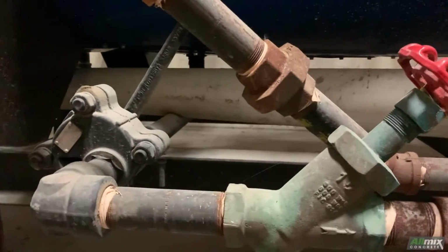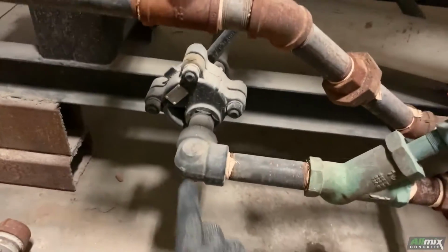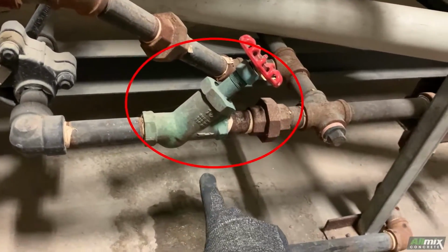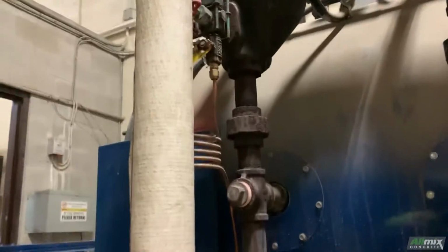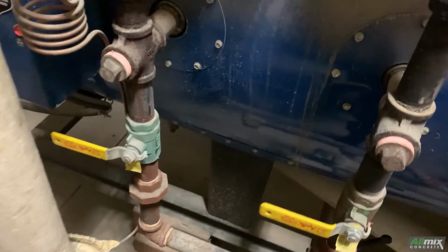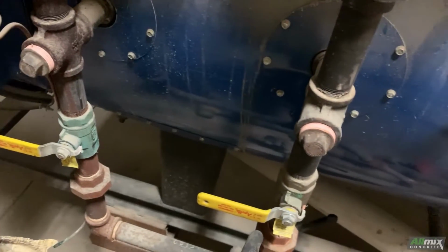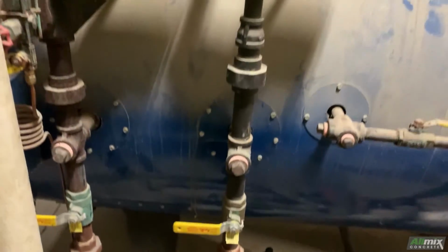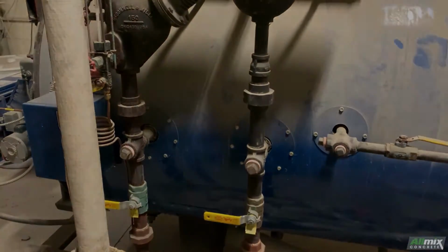Down below, we have the bottom blow-off valves. These consist of a fast relief valve and a slow release valve. In this setup in Brampton, the blow-off exits to a water tank beside the garage. These valves here can also be used to perform side blow-offs and to check the water column. Many boilers also have surface blow-offs, which are typically controlled automatically based on the amount of fresh water entering the boiler.